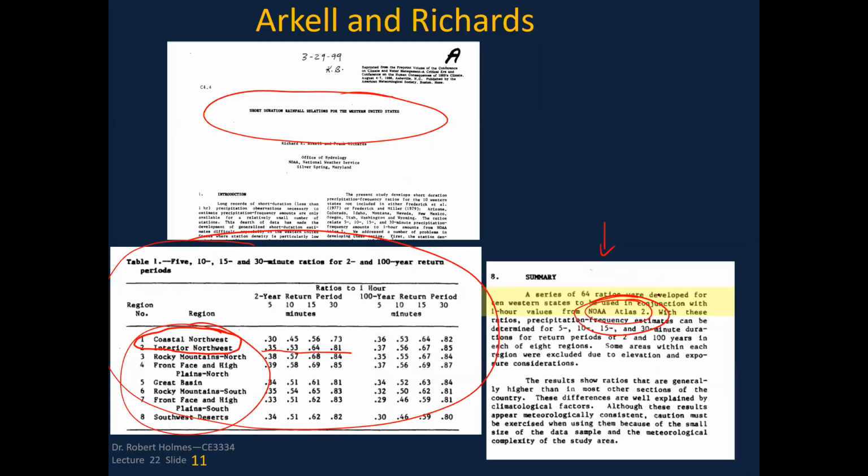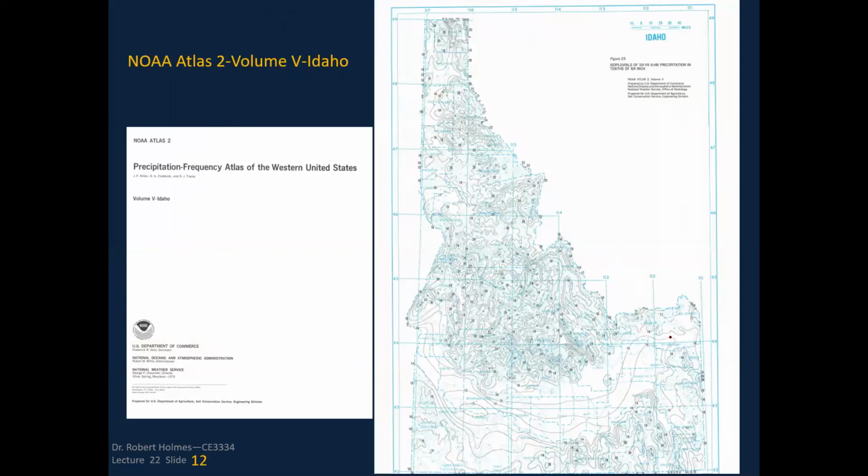If I clicked on that link, this is NOAA Atlas 2, and when you go to that atlas, you see a series of maps. And here I've got values in tenths of an inch. So if you were to zoom in here, you'd see that's a 15-inch, 14-inch. So again, this is a 6-hour precipitation. They can get some serious rain out there in terms of their probability statistics in that location.